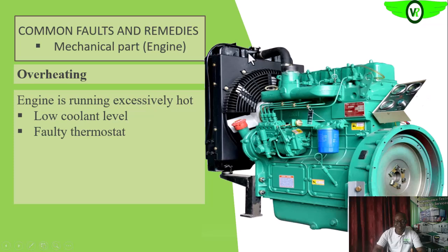So if water is delivered into the radiator, you know that the thermostat is working. If it's not delivering, then you check the thermostat and replace it so that water can circulate freely through the engine.